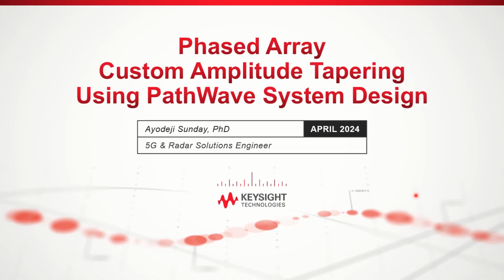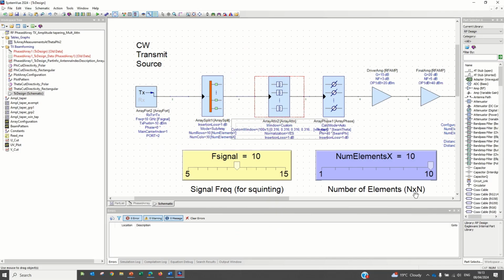Hi there. Today I'll guide you through the process of implementing custom amplitude tapering in your phased array design using the PathWave System Design, also known as SystemVue. Amplitude tapering is a powerful technique that allows you to suppress the side lobes by adjusting the signal magnitudes across different sections of your phased array antenna design.